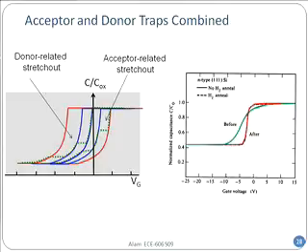Now I'll tell you all about hydrogen passivation and other things two lectures down, but for the time being, it is very important to understand that any time you see a stretch out, you have to improve your surface, and you try out various strategies to do so. This has got nothing to do with silicon per se. It could be gallium arsenide. If you have donor and acceptor-like surface states, you will have the same problem. It could be graphene, or anything. This stretch out simply reflects the voltage-dependent charging of the surface states, and somehow you have to fix it, because otherwise your transistor isn't working. So the strategy will be different. Here hydrogen passivation works; in other places there are other things that people have done.